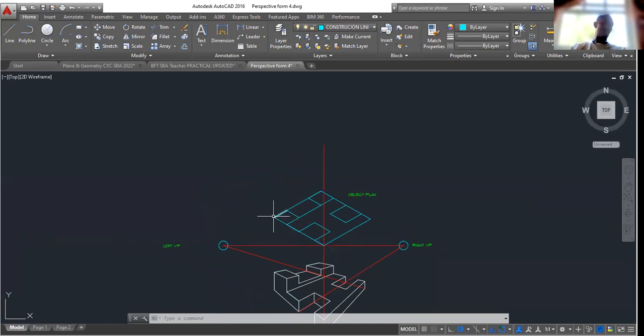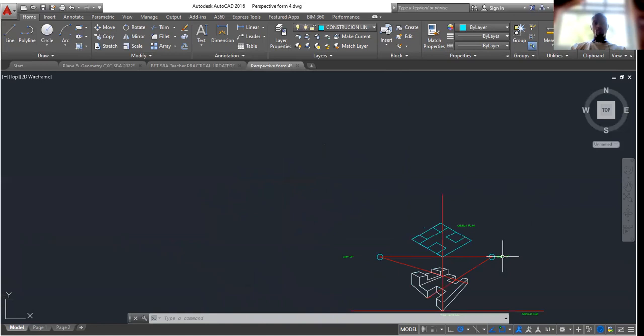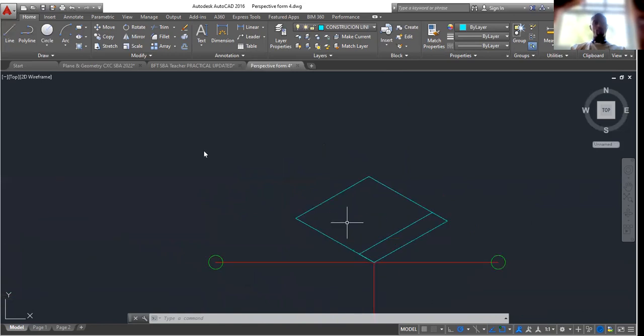So I'm going to work from the back here, which is 16 millimeters, which is this short line here. Then we have another 16 millimeters, which is this short line here. So going back to my drawing from here, I click on the corner, I type in my 16 millimeters, then I go across to complete, enter, then I go again and I do another 16 millimeters going down this way.